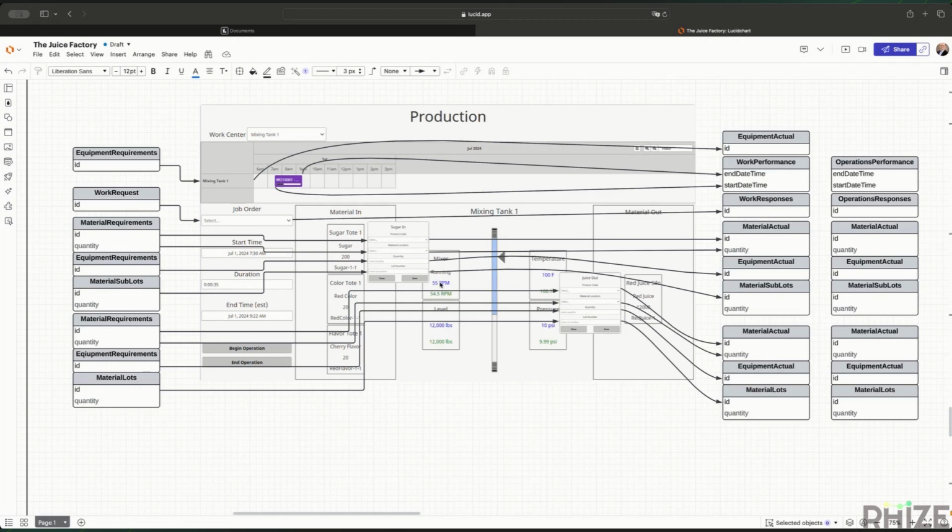But if there's a variance, is the operator allowed to do that, or does there need to be some kind of override? Chances are that's going to go in your variance report of, it's supposed to be 55. I don't map that here, but that would be part of your actual in there. This is just telling you the actual process variable, the PV, of what the equipment's actually doing right now.